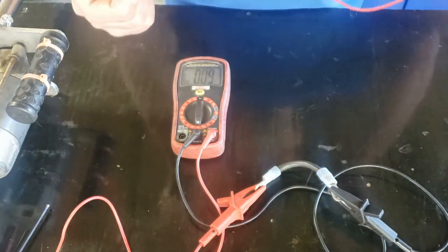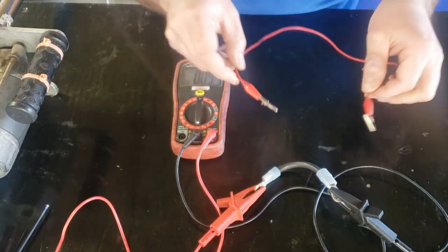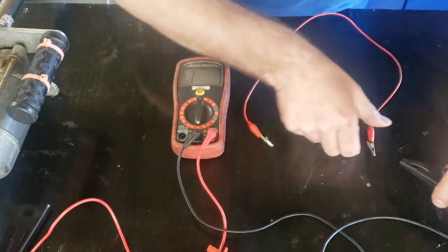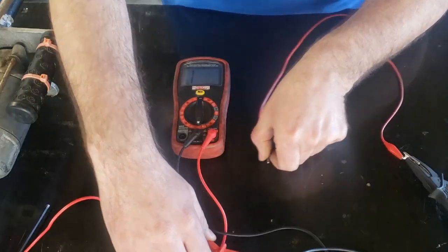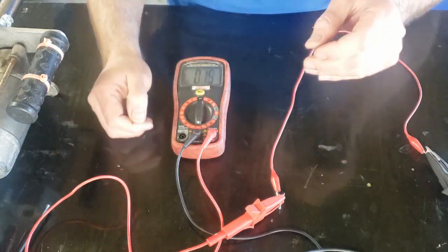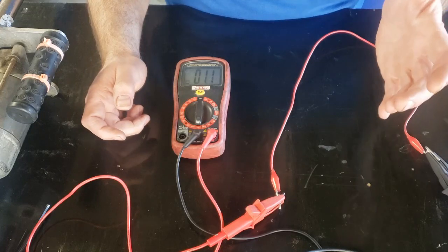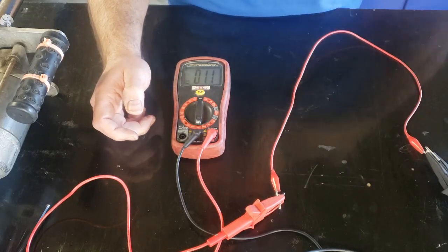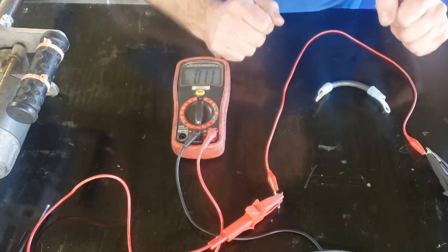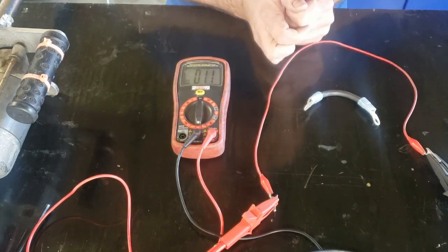Then I'm going to take this little jumper wire, this little 16 gauge jumper wire, which is way too small to use as a starter wire, but just for the sake of understanding, I'm going to make a connection across the 2 ends of this jumper wire. And I get a reading of about 1.1 ohms, somewhere in that neighborhood. So I have about 0.1 ohm more resistance in this wire than I do in this wire. So I would say comparably that these 2 wires have about the same amount of resistance.